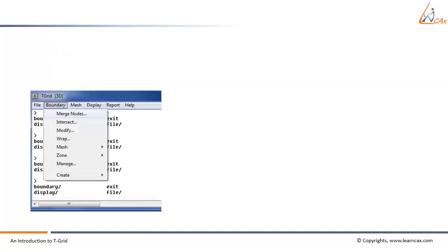Repairing boundary mesh involves merging free nodes, closing holes in the surface mesh, deleting multiple connected faces and edges. Improving boundary mesh involves swapping, smoothing, and remeshing. The boundary operations include the following options.